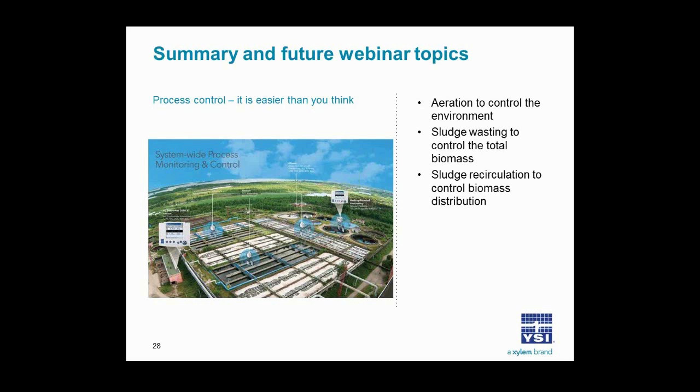Well, there's a lot of different approaches to this. As I mentioned, an online TSS sensor can be factory calibrated. So if your mixed liquor properties are similar to what's in the factory calibration, you plug it in, and you go. Recalibration intervals would have to do with, one, whether your sludge changes, and that may happen seasonally. For instance, you might need a recalibration for winter and summer conditions.